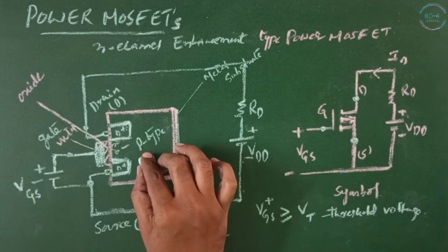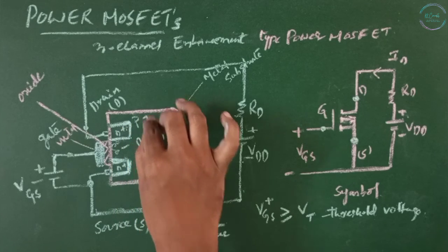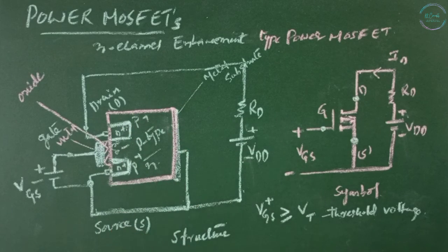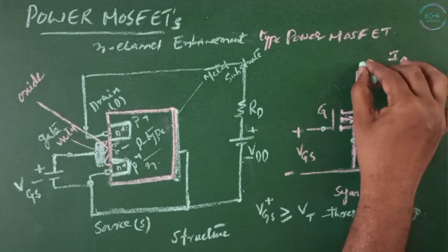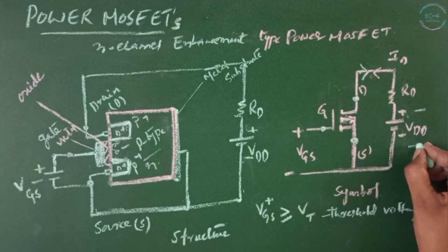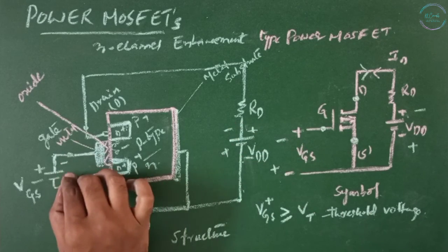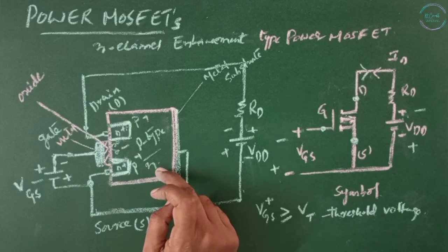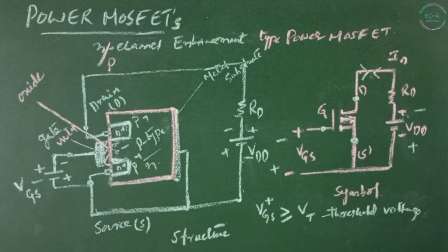If you replace the P-type with N-type, and the doped N-type regions with P-type, without a physical channel, the directions are opposite and the voltages are also opposite. Since the substrate is changed, the N-channel will become a P-channel, and the directions of VDS, IDS, VGS are reversed for the P-channel enhancement type MOSFET.